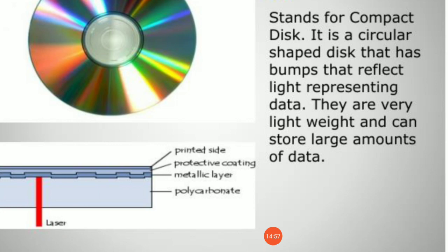The reflected laser is sensed by a photodiode to read data. The intensity of the reflected light of the laser changes as it encounters a pit. A pit spreads the light so that the photodiode receives little reflected light. On the other hand, the surface without a pit reflects sufficient light to the photodiode. Thus, the change in reflected light is sensed and converted into electrical pulses for data reading.